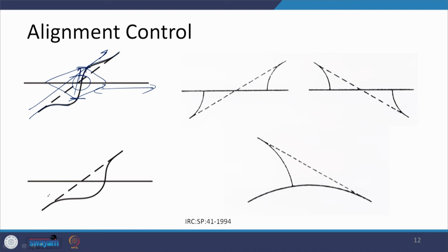Similarly, here there is another adjustment. We again have a crossing road here. So, this has been turned and the crossing has been provided here and become tangential at this one. Then, depending on what type of possibilities are there, what type of developments are there, how much open area is available, and whether there is a requirement of acquiring land to make these types of corrections or adjustments, decisions will differ in different environments.